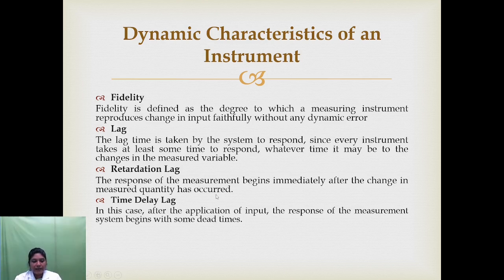So what is time delay lag? In this case, after the application of input, the response of the measurement system begins with some dead time. So the response begins after some time delay, that is called the dead time, after the application of the input. Such a delay shifts the response along the time axis and hence causes the dynamic error.